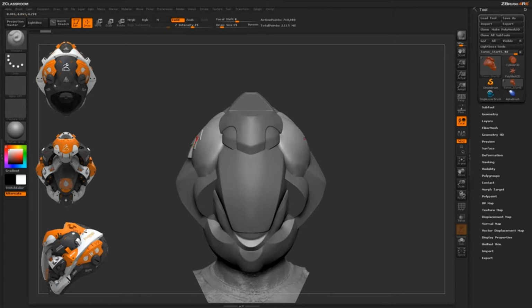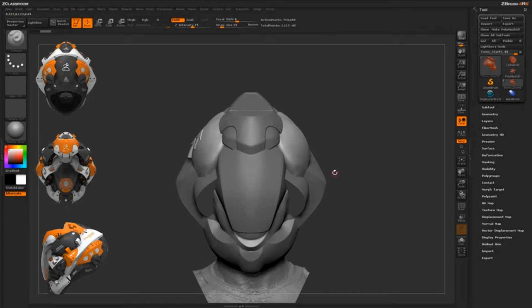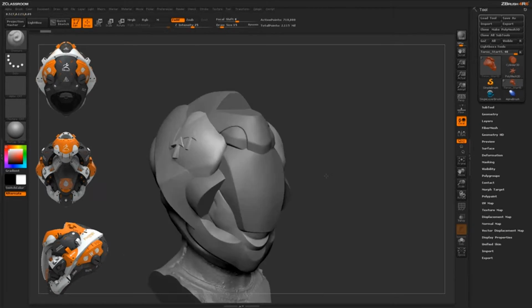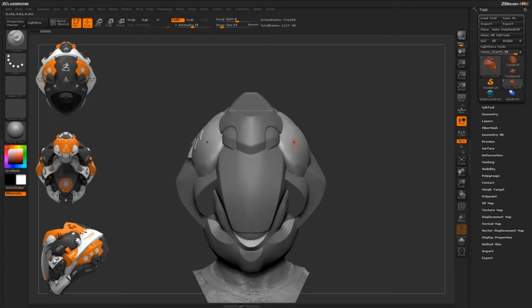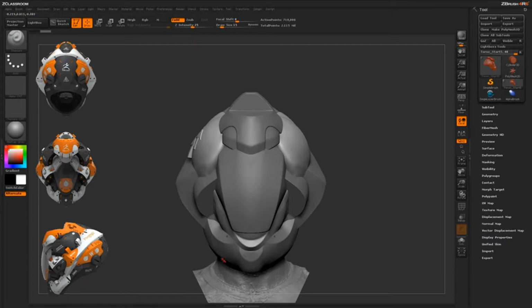Now you will notice that we only had these attributes applied to the single side of my mesh, and this is because we didn't have double-sided turned on. Now to get double-sided to work with Projection Master, you just want to make sure you have your model in a view like this, where you're actually going to be shooting through, because projection is going to do that 2.5D plane and then generate those details into the surface of your model.